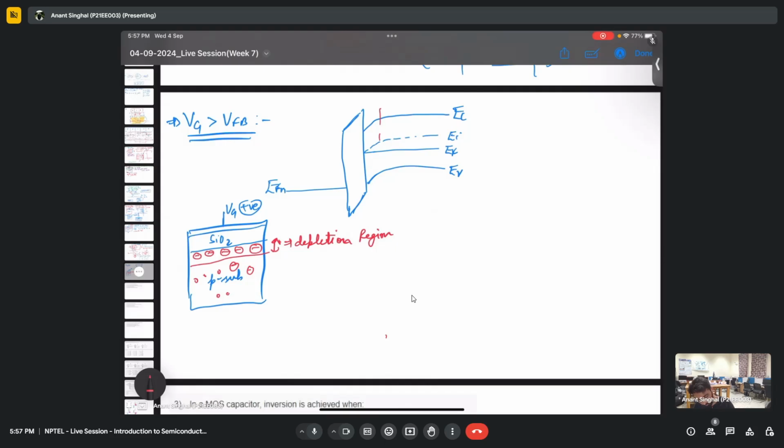Yeah, so if it makes sense, then this particular region we call the depletion region, in which we have band bending downwards, and we have the accumulation of this Na minus at the interface. I hope this makes sense now. So you can see when I'm bending the band downwards, at the interface, what is happening? This particular thing, which was getting more n plus, this has got intrinsic.